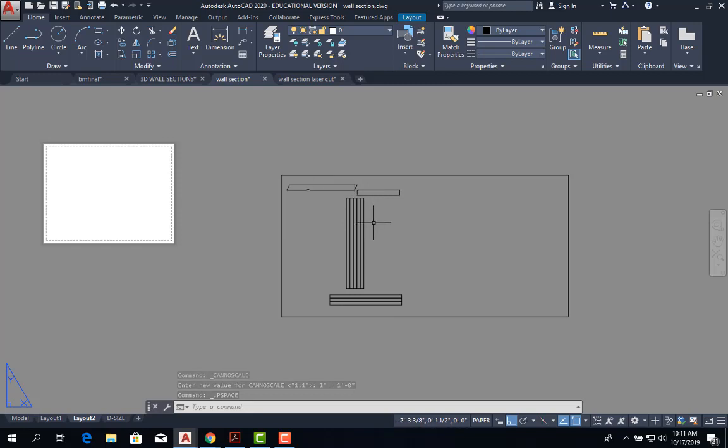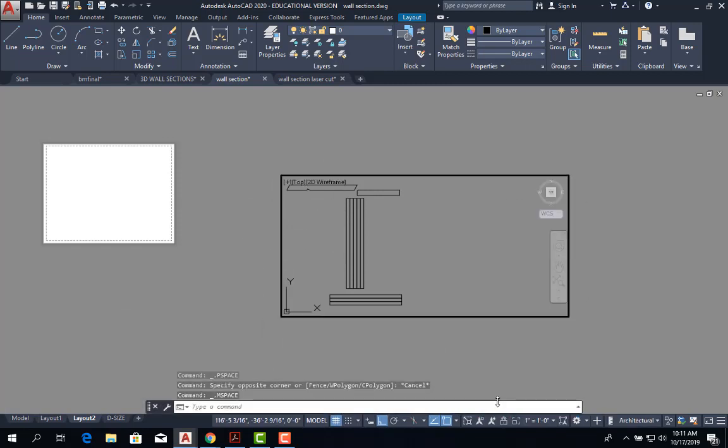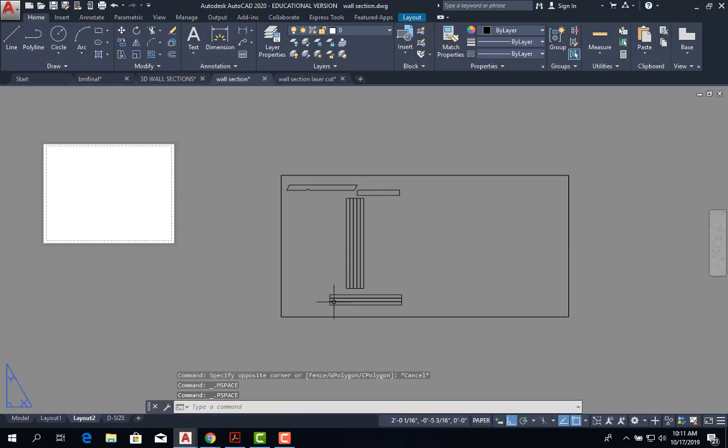We're going to cut them. Okay, so follow those steps. Have it like this when you come to me to cut it. That way it's just a matter of changing the colors, and we send it to cut. Just make sure again you know how many pieces you need of each. Draw them correctly the way I showed you. Go to paper space. Do the table that is 24 by 12. Open a viewport. Inside the viewport, set it to the scale that we needed, 1 inch equals a foot, and bring it like this so we can go ahead and cut it.